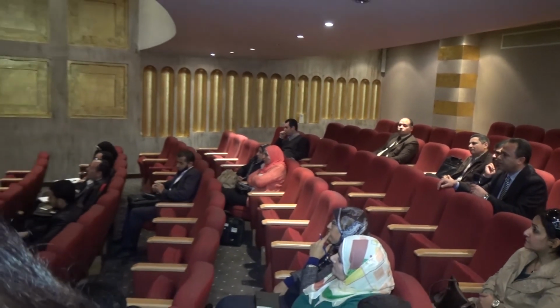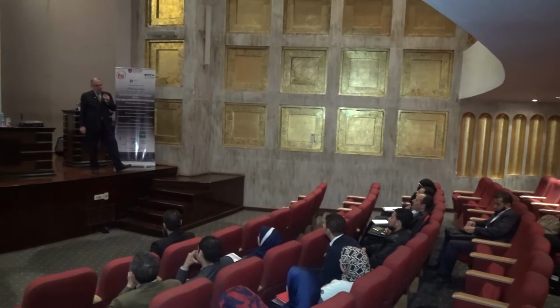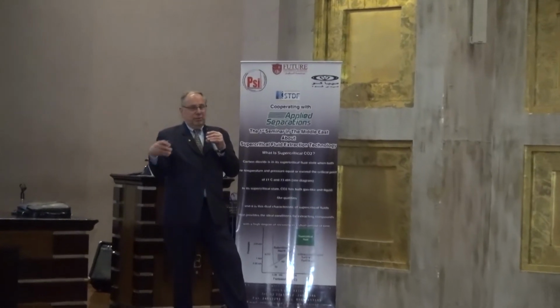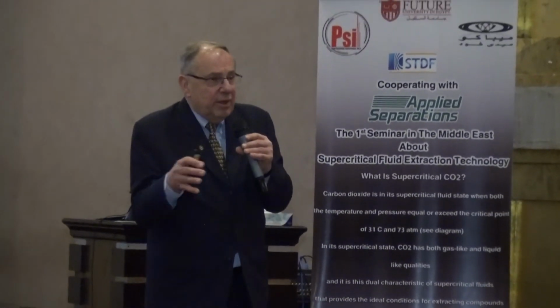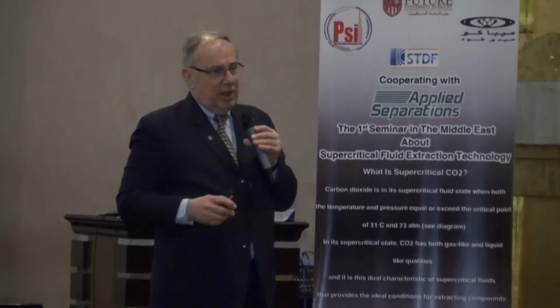I'll be very frank with you. There have not been good results when we're dealing with organic molecules for pharmaceuticals. The results have not been that good. And the problem most of the time has to do with agglomeration. That is, the very small particles will stick together. Now, people are trying all sorts of techniques subsequent to making the particles, for example, putting ultrasound into the collection area. So there is work being done in this area to prevent this kind of agglomeration.